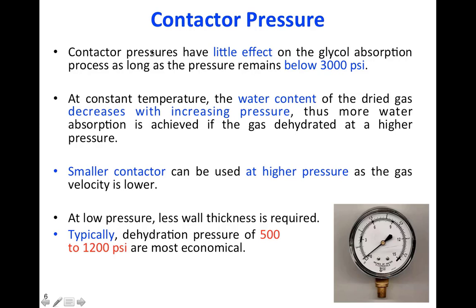Okay, the contactor operating pressure is also another parameter that needs to be considered, but compared with temperature, operating pressure doesn't have that much effect. As long as we are below 3000 psi, which is almost 200 bars, we are okay. We won't have any big issue.